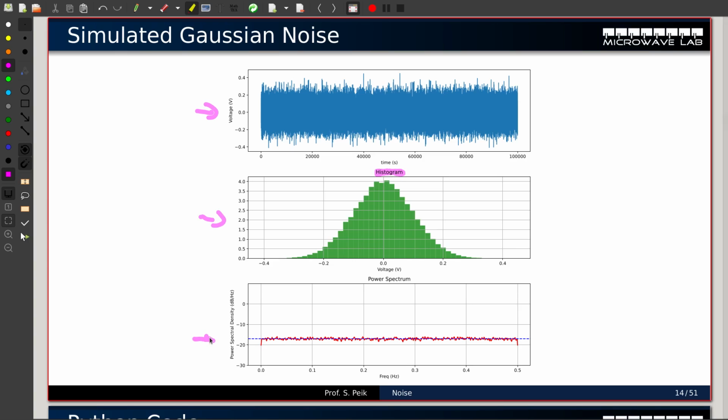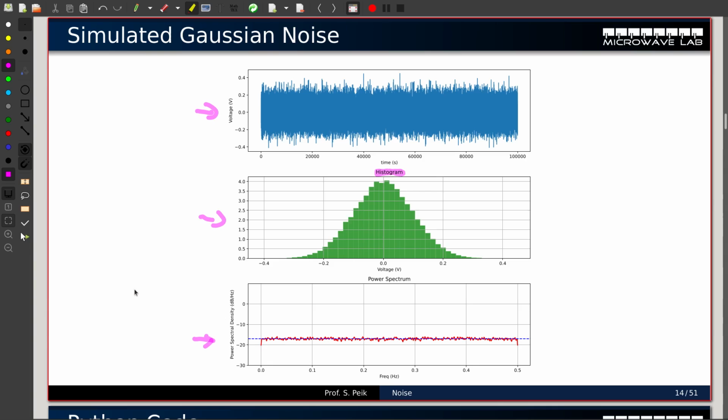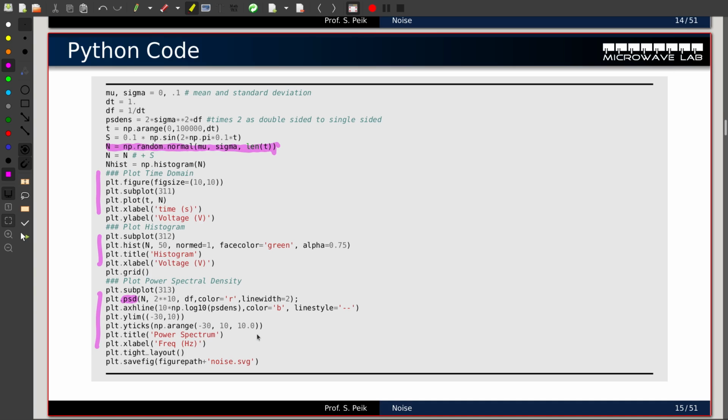And here you get the power spectral density, my frequency domain response, found by an FFT. And it looks like this, and you see clearly the straight line the signal follows. The straight line is not perfect because we are not looking at an infinitely long signal. However, it's there. Good. If you like, you can stop here and copy the program, or I can give it to you and you can try it yourself.